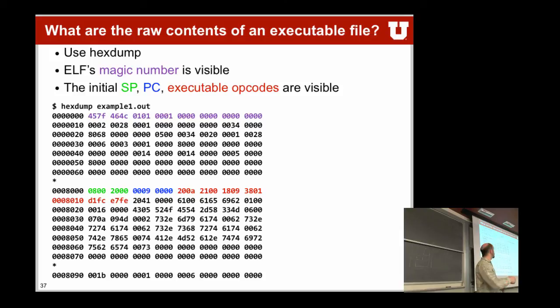And then down here, you can see the same stuff again. Do you notice something? Slightly different than from what we have seen before, right? It's now in half words, little endian. Instead of byte-wise, it's now half words. So we have 2000 and then 0800. Sometimes very confusing to figure out in little endian what's what. Sometimes it's really on per bytes. Sometimes it's on half words. So you have to be careful of what you're looking at.